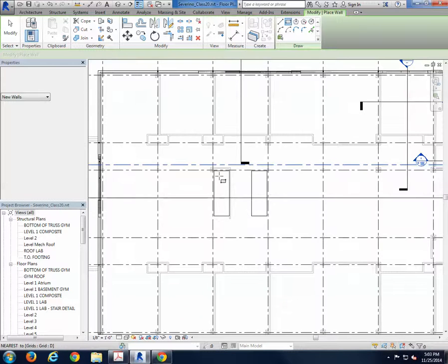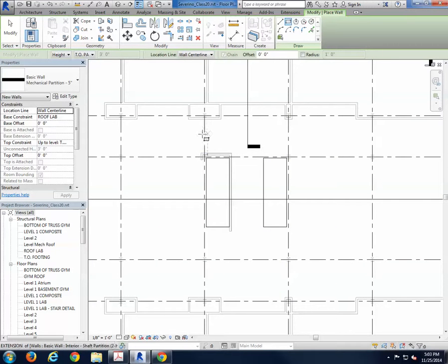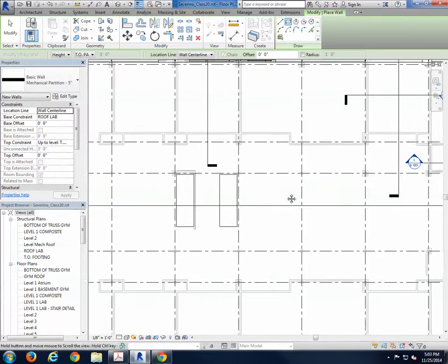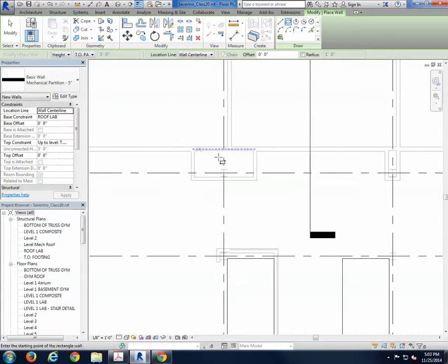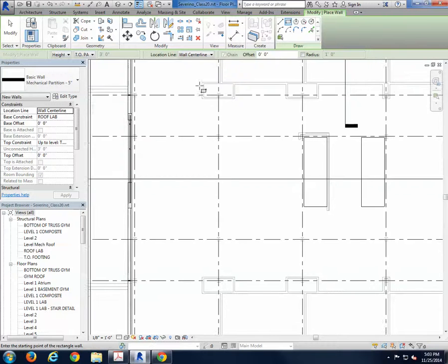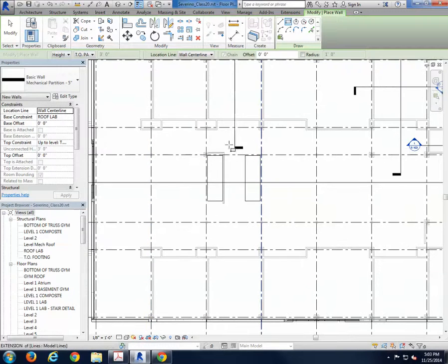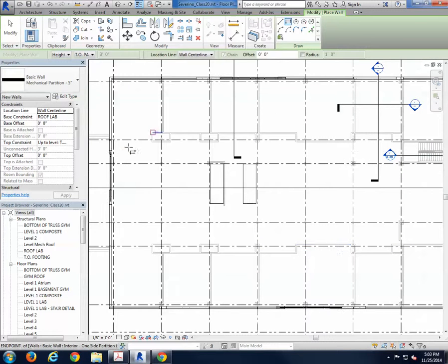Now what you really want is to enclose the shafts, but also any other mechanical shaft. So if some of you have created your shaft openings here, you really have to cover them with your entire mechanical rooms, because the ducts will go from the machines to the shafts and down through the ceiling. So if you did a core all concentrated in the center, it is better for you. If you made some shaft openings here in the perimeter, you're going to have to make a bigger mechanical room. I'm going to make it bigger.